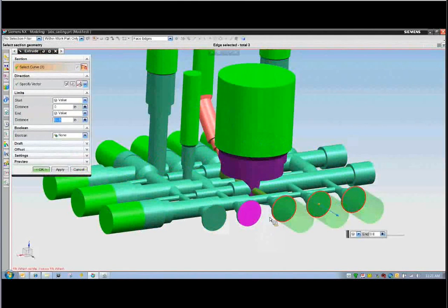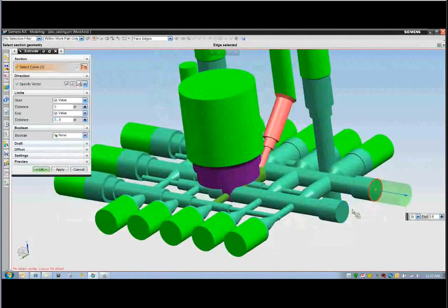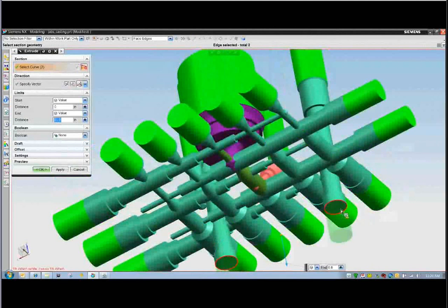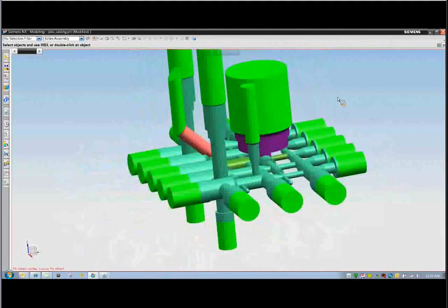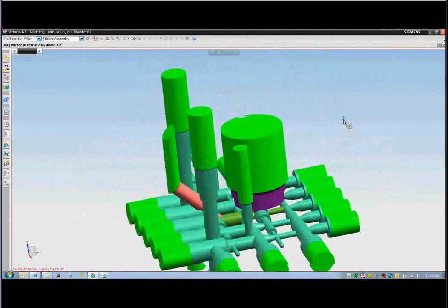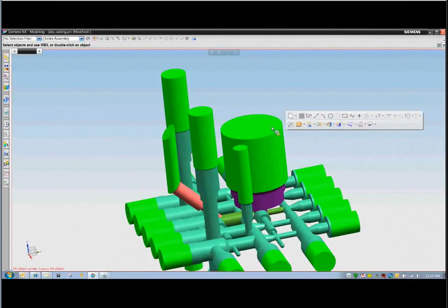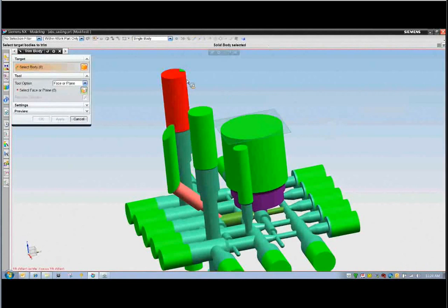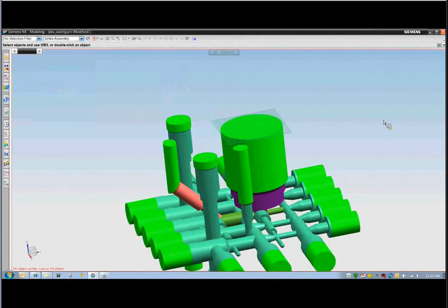X for extrude. We'll extrude these, and we have two more on the bottom here. We'll extrude all of those. And then lastly, what I want to do is trim the top extrusions to a plane. So I'll create the plane on this level here. We'll go into a trimming operation. We'll trim this, and this to this plane, and we're now complete on that.